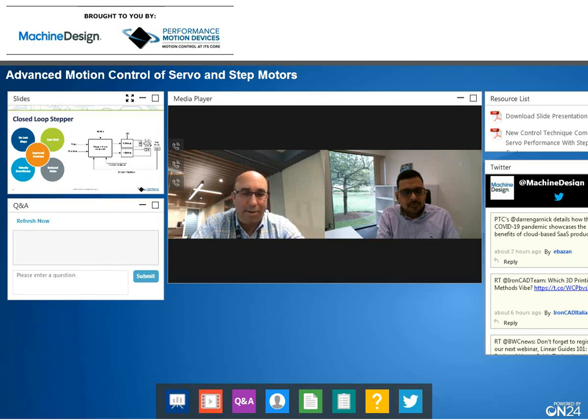So there are these different levels of closed loop that people talk about. What PMD and this webinar is really focusing on, and what I've got some examples to talk about, is truly running a stepper motor like it's a brushless permanent magnet motor with feedback, and overcoming the things that always plague that kind of solution.